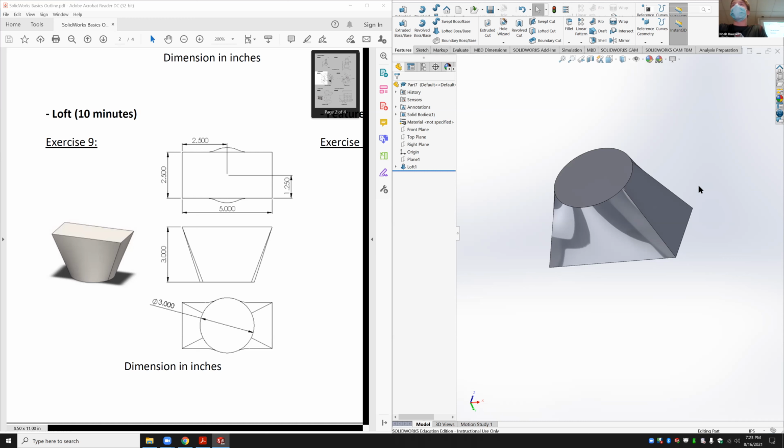Make your circle first, and your reference plane, and then your rectangle, and then you can lock between them. It's not that bad. It's like 3 steps. This one's not that bad. This is one where I think it's worth making sure everyone can get on the same page. What's the distance? The distance between the circle and the rectangle is 3 inches. So that's the offset distance that you want to pick for your reference plane.